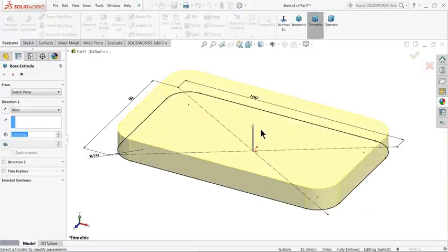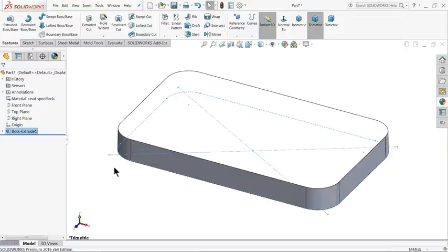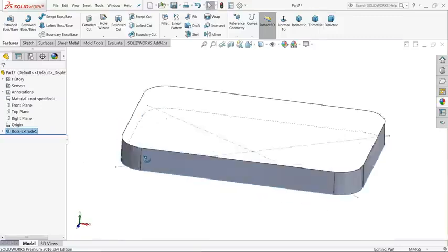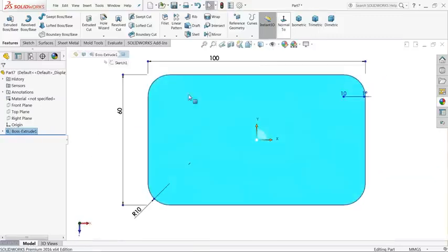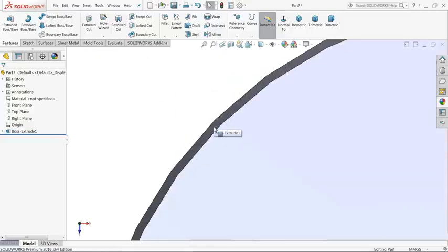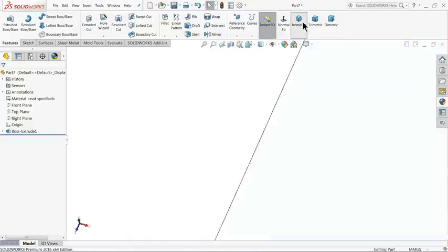Now while you are going to design any kind of mold, the side wall should be tapered, minimum 1mm, anything minimum should be. So we will keep 1mm tapered, otherwise it will be difficult for molding. Select here 1 degree, draft or tapered or anything you can say. Okay, if you choose this face, now see it's 1mm draft.